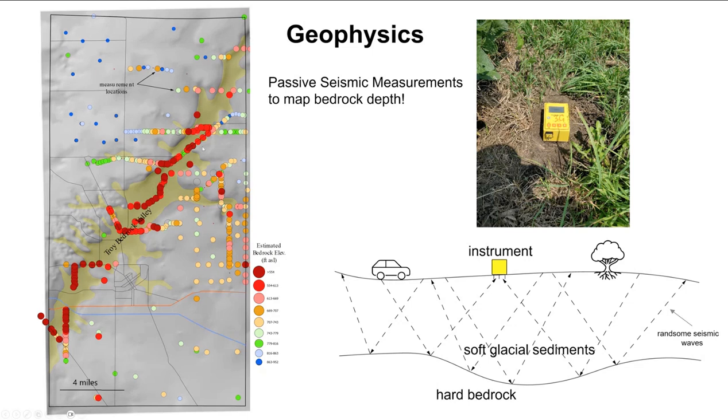So we've had over 400 measurements in the last 3 years in Boone County, and we've done these profiles across the county, and you can see where the reddest stuff is in where we are pretty sure the Bedrock Valley is. So it's confirming the geometry, our understanding of that valley. And it's a really nice tool to help us understand the bedrock topography.